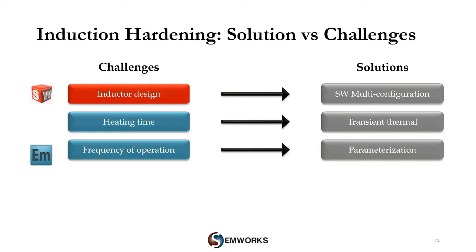Later on, to optimize your hardening process in terms of optimal frequency and hardened penetration depth, a parametric analysis coupled with thermal inside EMS will be used to reduce the simulation time and compare the effect of those factors on your design within the same study.